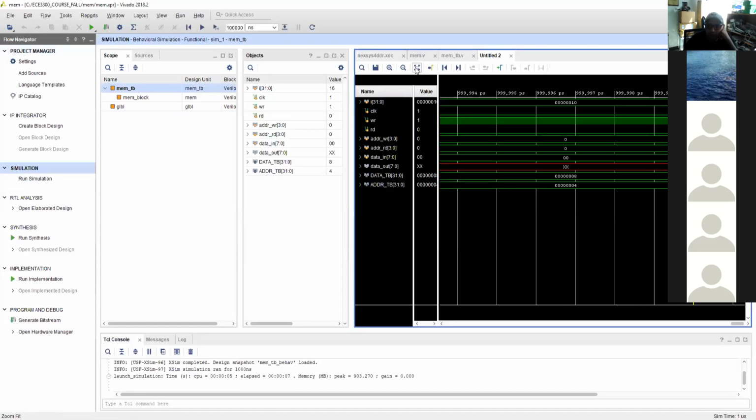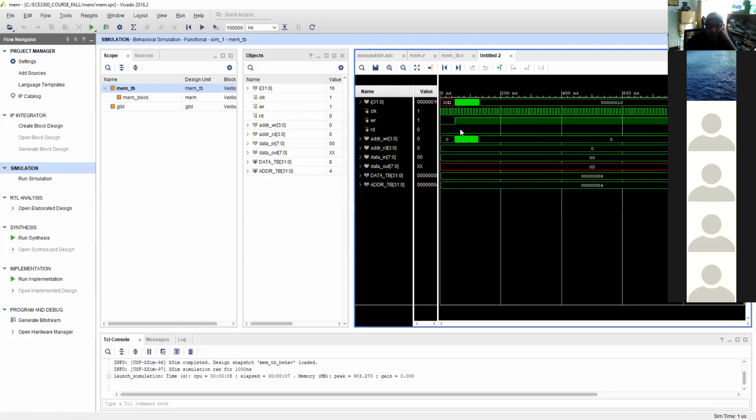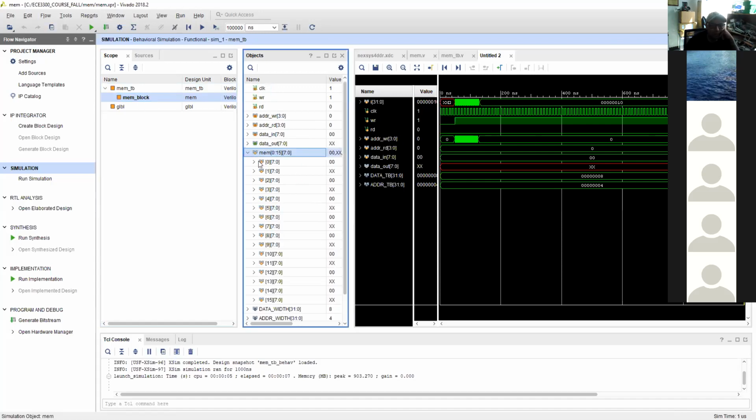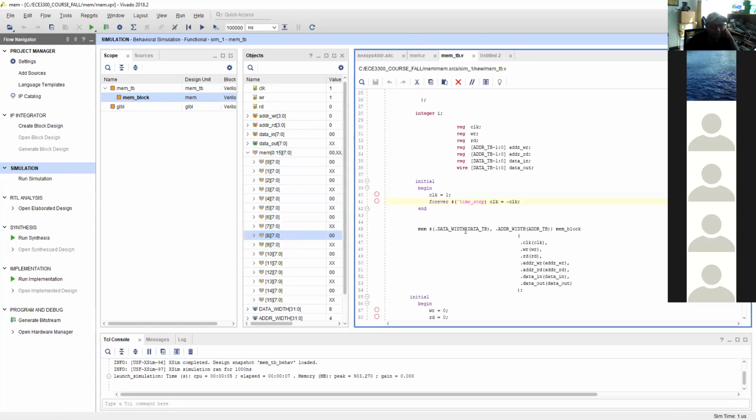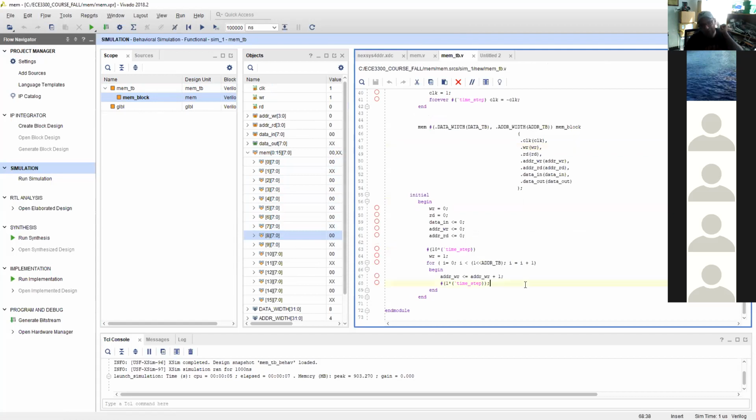So that should be the use case too, right? Look, now it's actually going, and you're right. And you notice also the address counter was running without the clock, because that's a testbench. Now the whole thing, see, it actually makes 0 and then X and then 0 and then X, over and over. Do you know why? Somebody tell me why. Look at my code and you will figure it out.